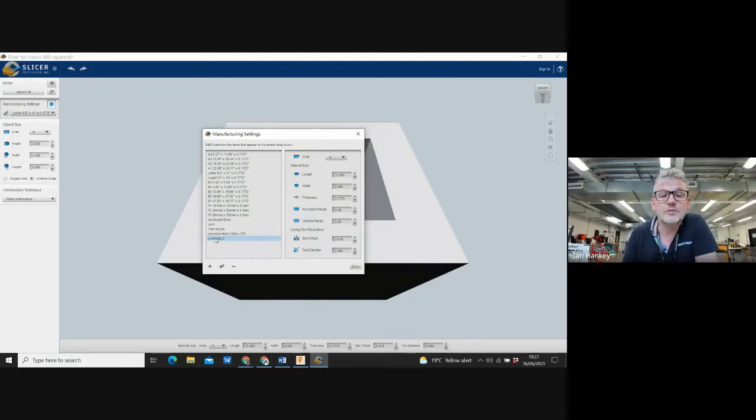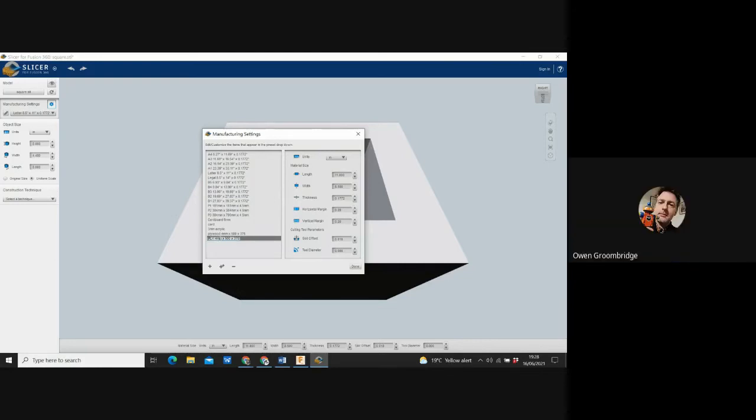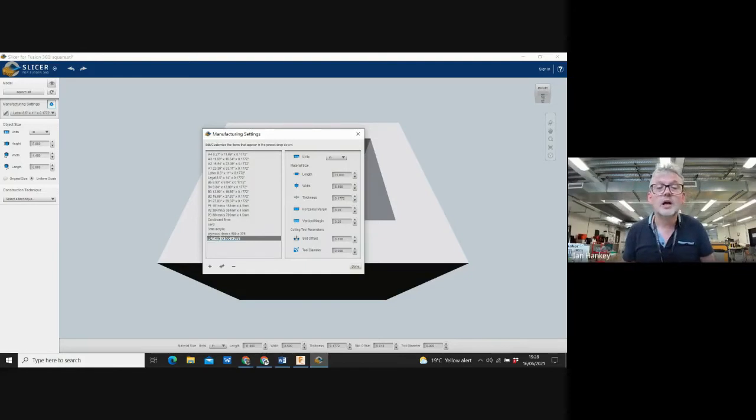When it says unnamed, I'm going to click on it twice, and now I can type in something, and I'm going to type in ply, P-L-Y. It's only for my use, so I know it's plywood. Then I'm going to type in 4mm times 500 times 375. I'm not sure if it's 373 or 375, but I think 375 should be fine. Thank you, Owen. So that's done.